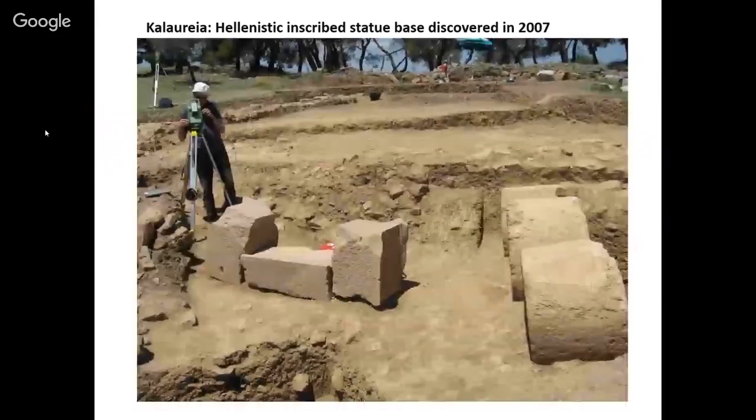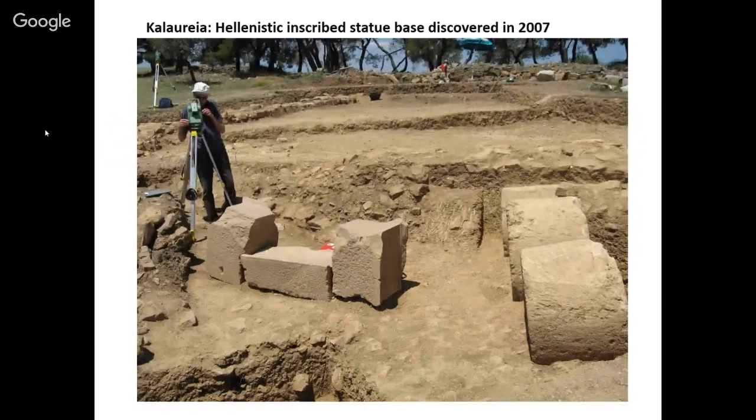So I went back to the field and just tried to see what you can do with a total station. When you do reflectorless drawing, it's very quick. You basically just point the laser pointer and click it, and when you have software that can connect the dots, you get a nice 3D drawing out of it, very quickly. I'll show you some of the examples that we've been doing later on with the total station.